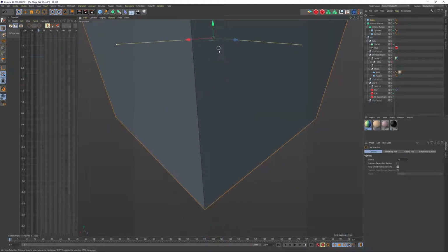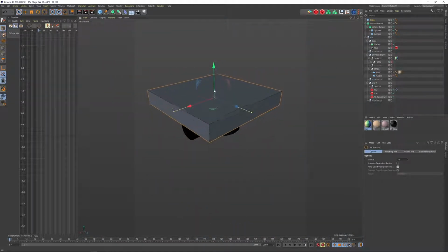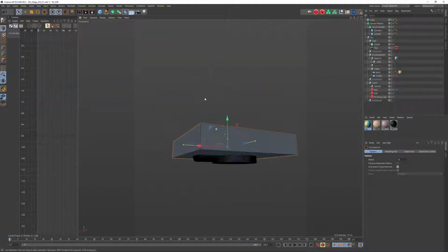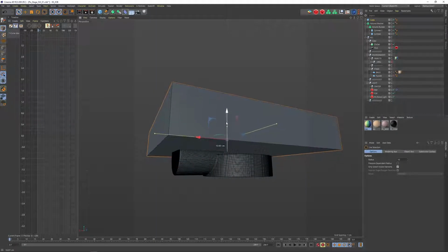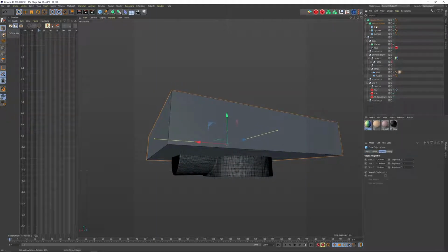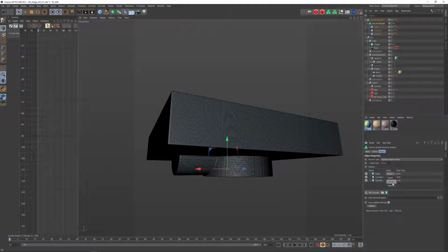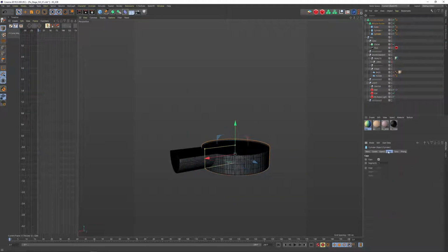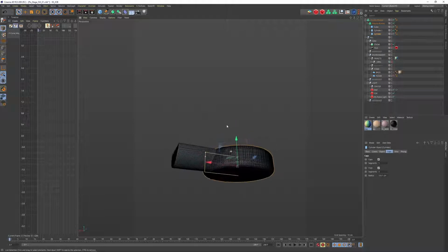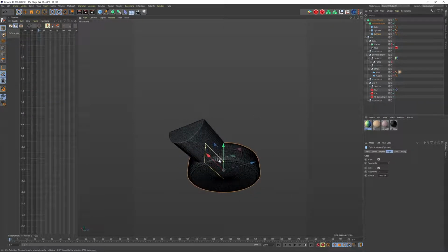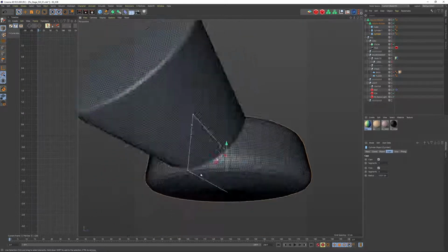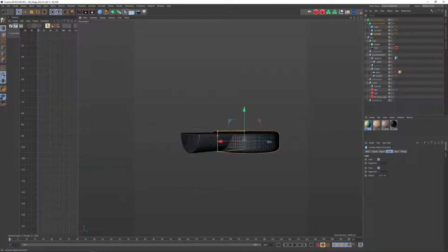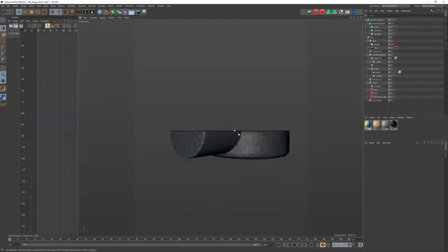Then what we'll need next, we will need to cut off the top part of that. So I have a cube which you can use for a subtraction, and let's just place it at the right position, so here, and I'll put that into the volume builder, and into the volume builder we'll go for subtract. That is the object which I want. Just one thing, I will add a cap at the bottom object, so something round will happen at the bottom, and I think also the object can be a little bit higher, so that looks good.